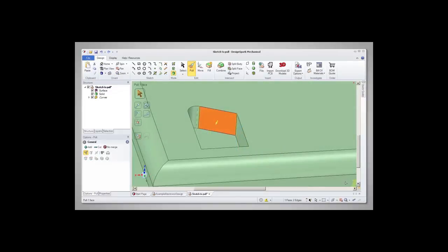Once again, let's compare move and pull, this time when acting on a face with edges selected. The pull tool will constrain the size of the face as it moves, whilst the move tool will allow the face to expand and contract as it interacts with the surrounding geometry.